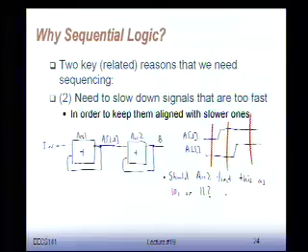It's very important, because if we don't have that ordering in digital circuits, we have a big problem. And that's what registers do, and that's what clocks do. Registers store the values, and clocks tell you at what time the data value is going to be valid.